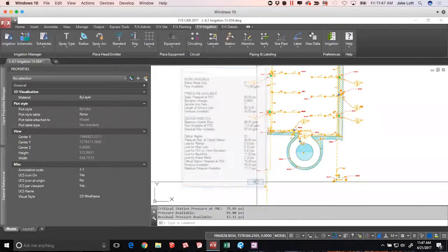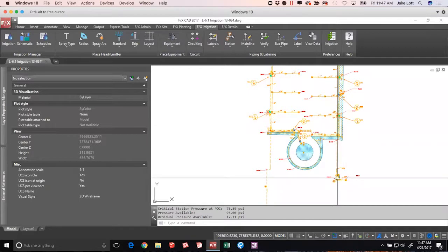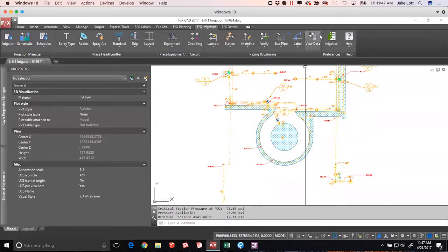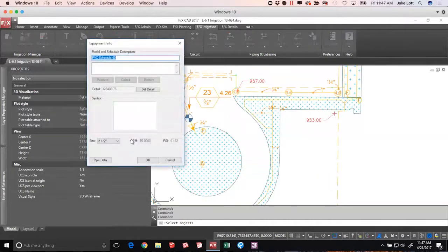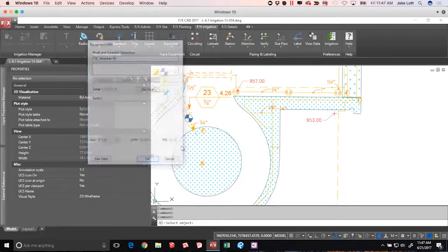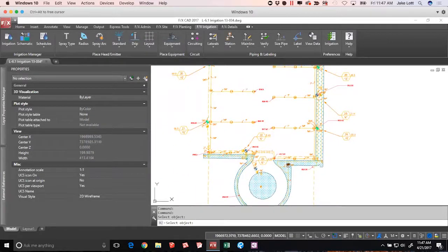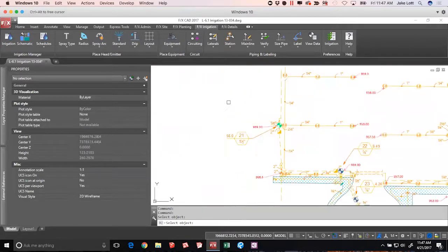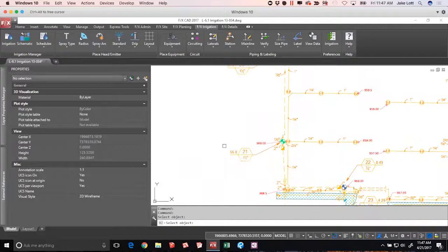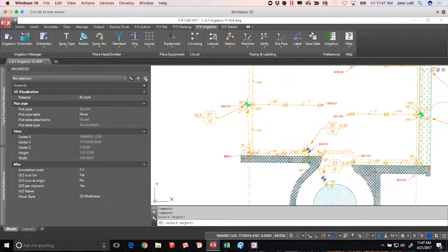This one was a little bit tricky, but again, I like puzzles. So if you use your view data tool and you click here, the system is going to be telling you how it's going to be splitting its flow, especially if it's a loop system. So as you go through, it is accounting for 56 flow. Again, you can look at your valve totals to see where that flow is accounted for, and it looks like this guy right here is what's harnessing that overall flow.